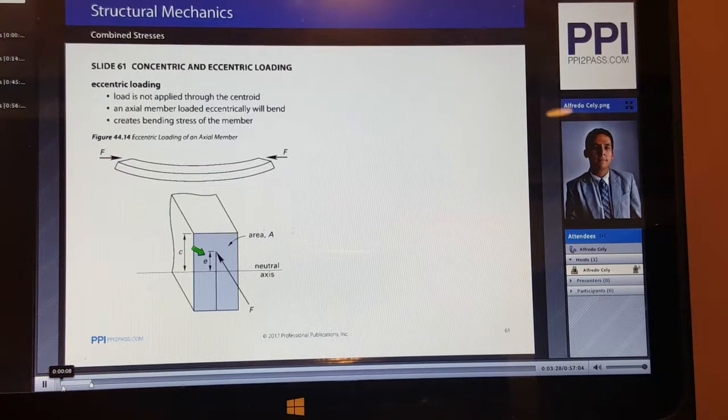The bending stresses in a beam column may cause a compression member to go into tension on one face. This can be avoided by keeping the eccentricity within the kern of the member. It is particularly important to eliminate or severely limit tensile stresses in unreinforced concrete and masonry piers, since these materials cannot support tension. Piers are designed as beam columns.